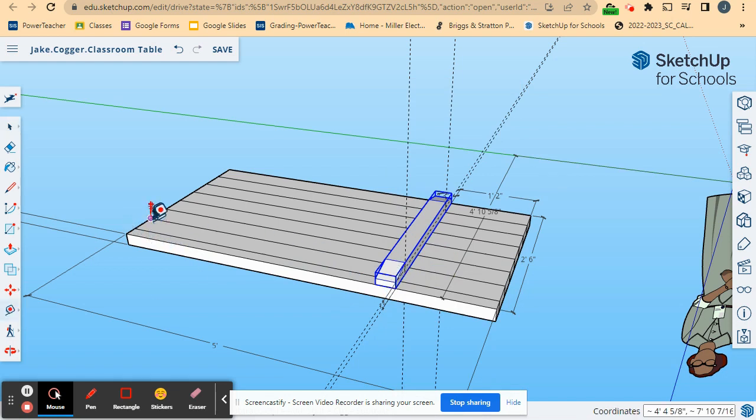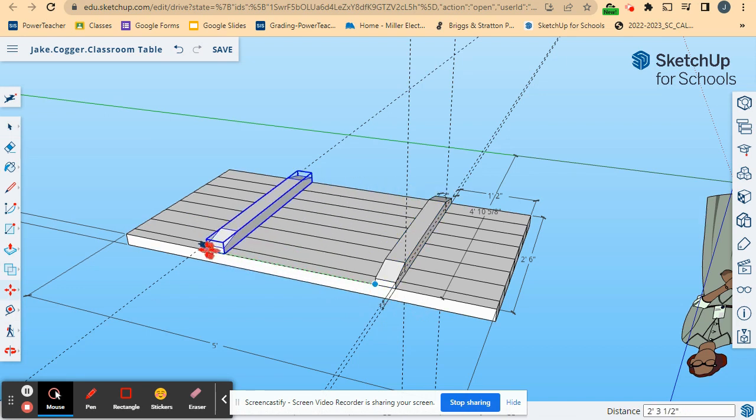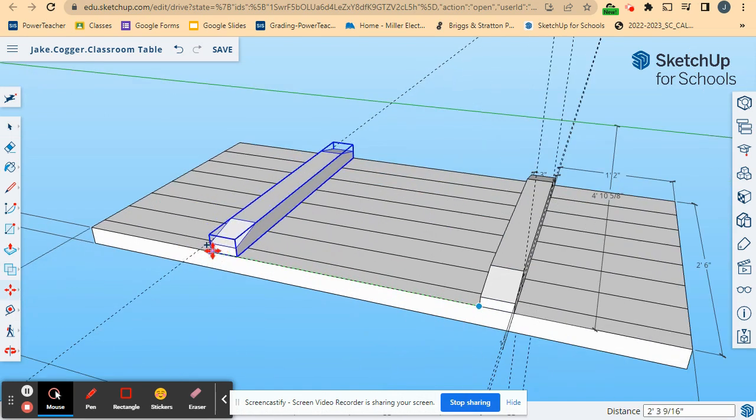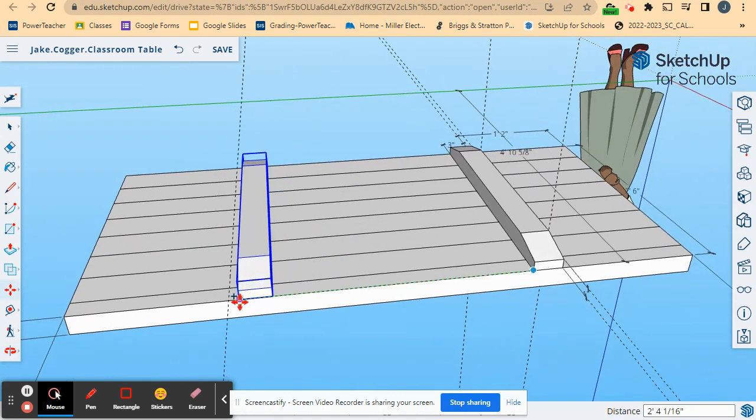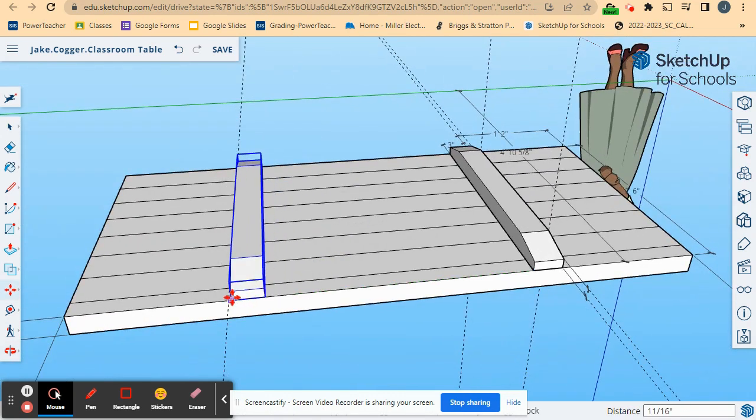So I'm going to activate my tape measure tool. And I want to come in by 14 on that axis. So we're going to hit the M key, Control key, copy, paste, and we're going to click and drag that over until it snaps on that corner. Now, usually I have to do it more than once, but always drag from a corner, please. It makes life so much easier.